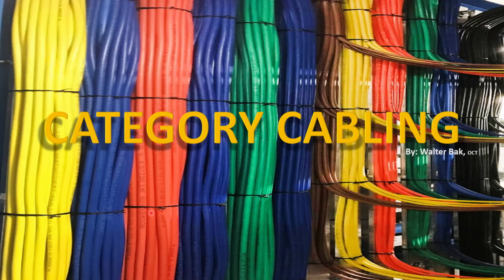Yes, then somebody might ask, okay, what did we just do yesterday during our labs? Yes, we have used zip ties in a small configuration, but what did I tell you? I told you not to squeeze that, not to bind it too hard, just provide a kind of running guidance. The wires should be just kind of sitting there freely.